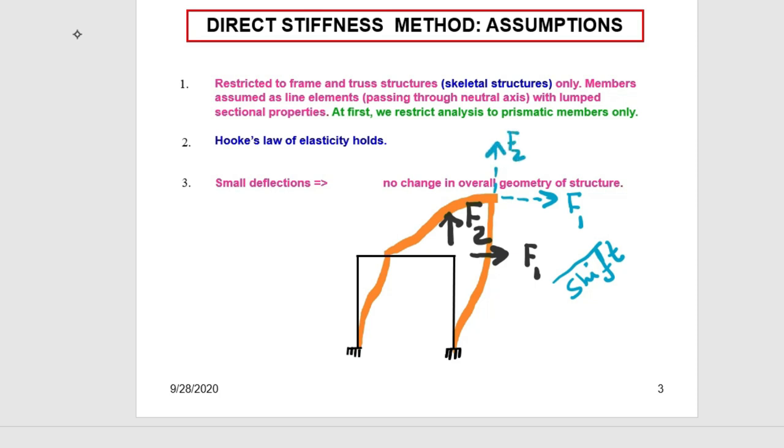Now if you apply the conditions of equilibrium, especially the moment equilibrium, what does moment equilibrium involve? It involves force multiplied by the distance. Now imagine that the structure has undergone very large deflections. If large deflections are there, typically of the order of say 1/10 of the member length or higher, the point of application of the force itself moves. Now you apply moment equilibrium. What will happen?